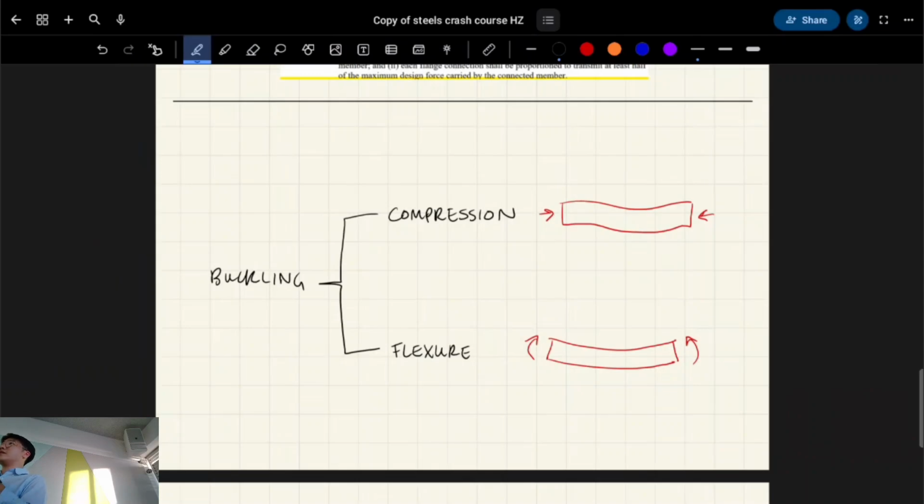So the skinnier it is, so how long, kind of like divided by how wide it is, essentially, right? So this is like slender. This slender column might be classified as this. A stubby column is classified as something which the length to width ratio is like smaller, basically. And so slender columns are really susceptible to buckling. Okay, that's the general idea.